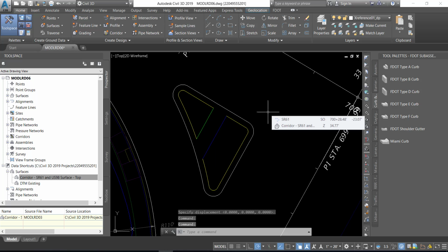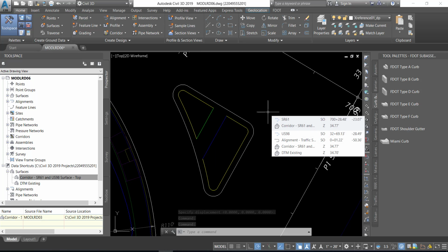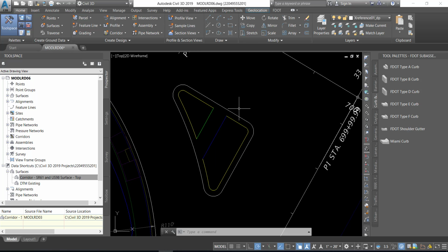Next, hover over the geometry you just inserted to get the polyline tooltip. This should be on the layer Pavement Asphalt. Next, bring your cursor over the Curve Back polyline. This is on the layer Curve Back as well. Finally, bring your cursor into the polylines inside and take note that they are polylines as well, and they are on the layer Sidewalk. Before continuing to the next exercise, save your file.